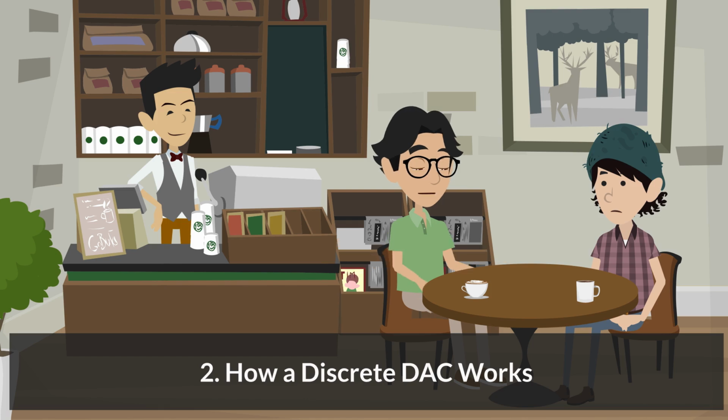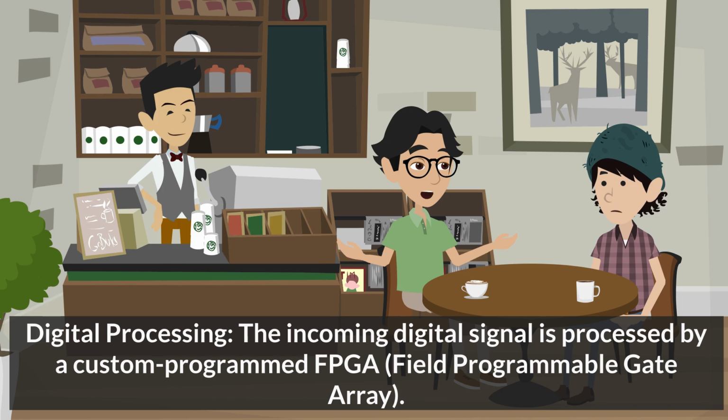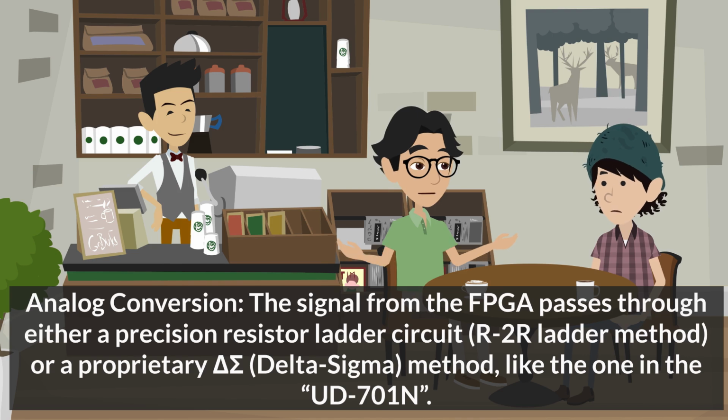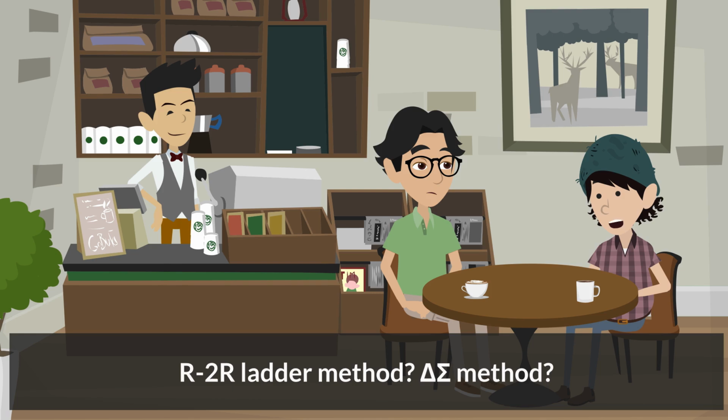Second, how a discrete DAC works. A discrete DAC primarily operates in two steps. Digital processing: the incoming digital signal is processed by a custom-programmed FPGA, field programmable gate array. Here, the manufacturer applies its proprietary filtering to convert the signal into ultra-high precision. Analog conversion: the signal from the FPGA passes through either a precision resistor ladder circuit, R2R or ladder method, or a proprietary delta sigma method, like the one in the UD-701N. By adjusting the timing and amount of electricity flowing through each component, the digital zeros and ones are converted into smooth analog signals.